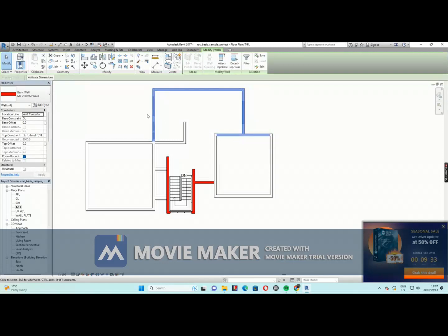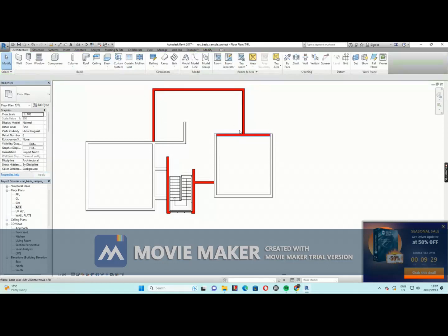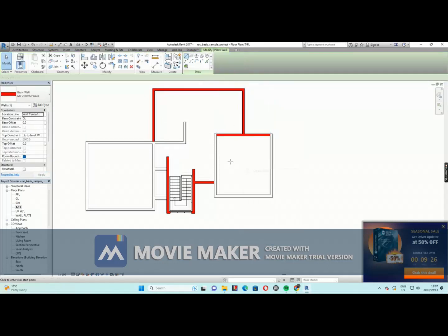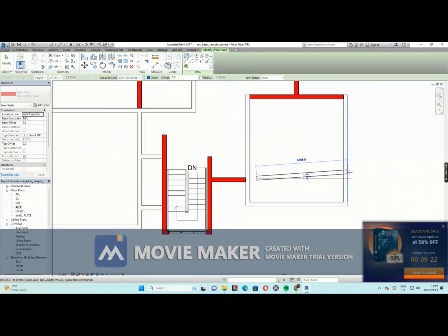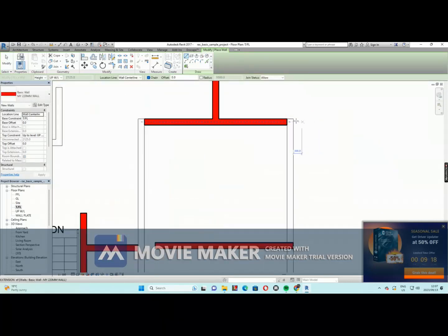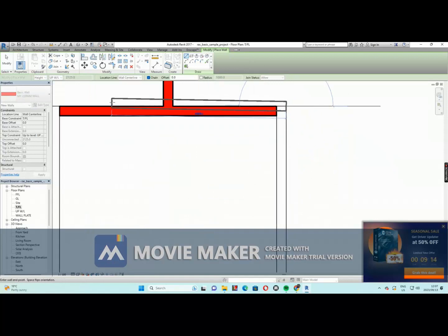And then you right click, you create another wall, because now I'm starting on top. You create another wall here. You can draw on top of this one, it doesn't matter, but it will create a line on your elevation. If your wall is picking on the center, then you can change it here to face. You see now it's clicking on the edge.